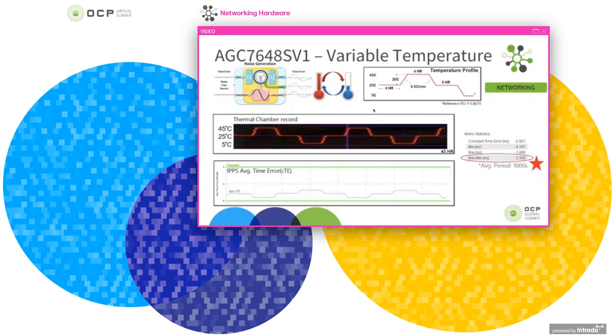It indicates that our system is very stable even under thermal shock, because the timing hugely depends on the stability of the oscillator. Here we use an OCXO, oven controlled oscillator, in order to stabilize the timing system against thermal shock, so we can gain a very nice result here.